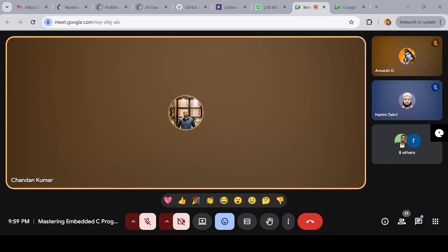First, you will have to configure the PWM timer, and the clocks will be auto generated by your controller and IDE. What you have to do is just connect your LED bulbs at that particular pin, and PWM will work.